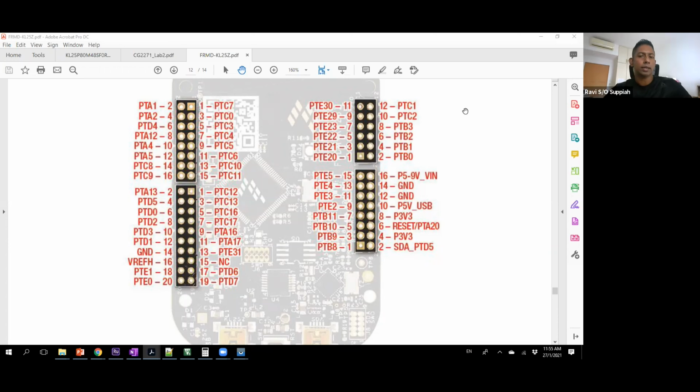Basically, I would say it's more of a space constraint, and in some cases in terms of multiplexing, they may have already decided that certain parts of the microcontroller will be used for specific multiplexing options, because you have already connected maybe the touch sensor over there, you already have a different type of interface and so on.